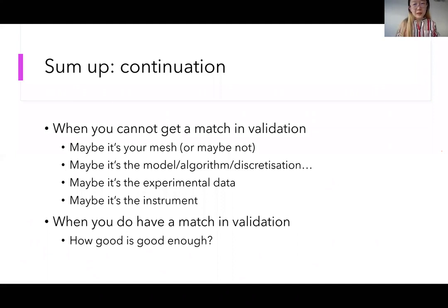And sometimes it's just that the experimental data is not accurate. As you can see, a lot of instruments are intrusive, and a lot of instruments are pretty basic, like the pitot tubes, they're very, very basic. And even though they're pretty reliable in simple streamwise flows, they could be not that reliable when turbulence is very intense in that area.